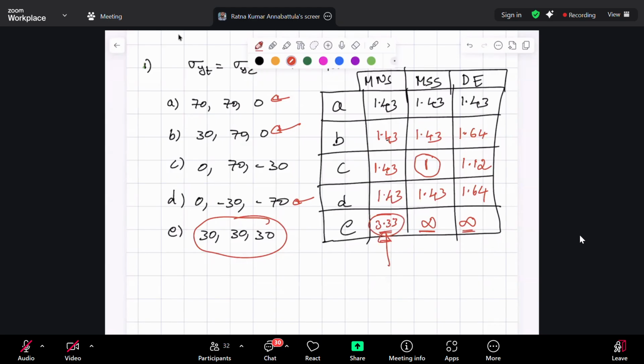And even with the formula, sir, like max of sigma 1 minus sigma 2, or sigma 2 minus sigma 3, because all the stresses are similar, something minus something is 0 only. Yes, the formula is obtained from the theory, right? So the concept and the formula should make sense. Right, sure. Okay, good.